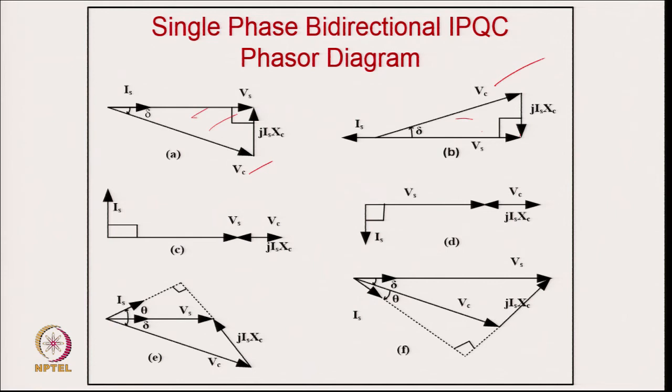So, with that analogy of the synchronous generator, you will probably remember it very well, and both are operating at unity power factor. If you want it to work only as a condenser, you can show that active power will not be there, only reactive power will be there, and you can have the current leading. Vs is there, but you will be adding the inductor voltage also in the same supply phase. Similarly, you can subtract also, and this will correspond to your inductive phase.